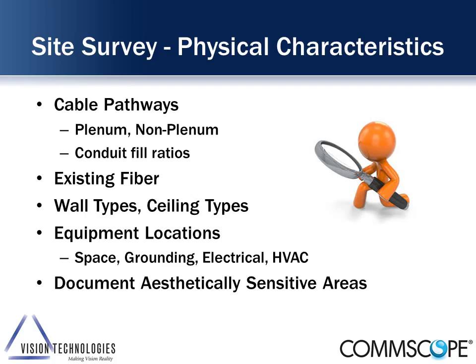Also, when you're in the physical survey, you want to understand if there's any aesthetically sensitive areas. And we've talked a little bit about the attorney offices with wood or marble walls, but there's also a lot of times I've seen lobbies that are very decorative and are not necessarily conducive to putting DAS antennas in lobbies, or decorative stairs.